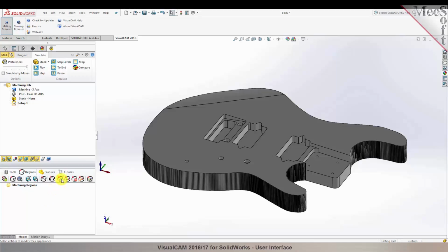And you can also define bridge points manually here. So now on the Features tab, these icons here allow you to automatically detect hole features in your part and allow you to automate the process of creating toolpaths for your hole features in SolidWorks.